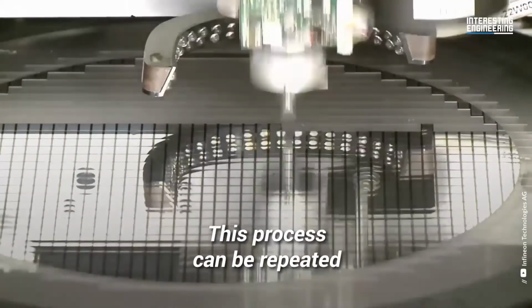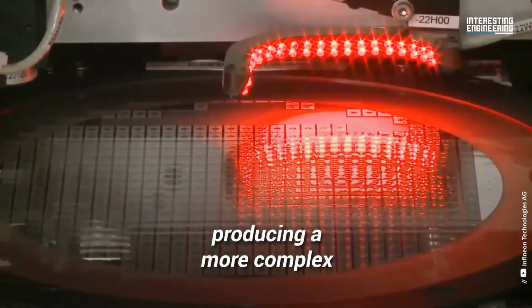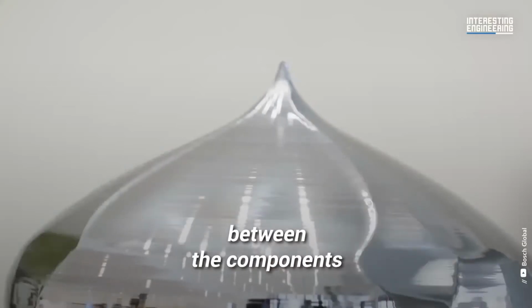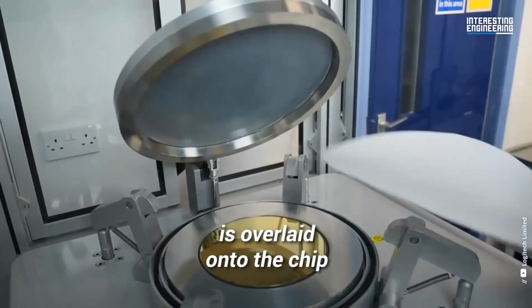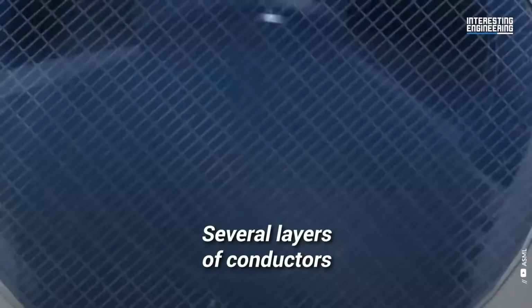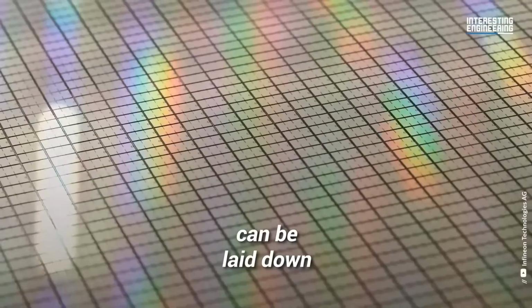This process can be repeated hundreds of times for the same chip, producing a more complex integrated circuit at each step. To create conducting paths between the components, a thin layer of metal, such as aluminum, is overlaid onto the chip, and the etching process is used to remove everything except the thin conducting pathways. Several layers of conductors separated by glass insulators can be laid down.